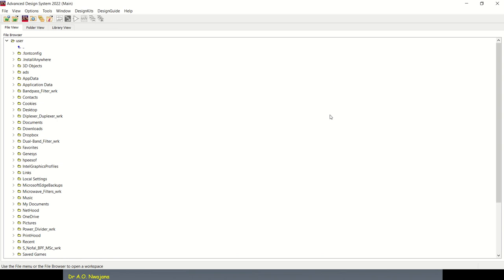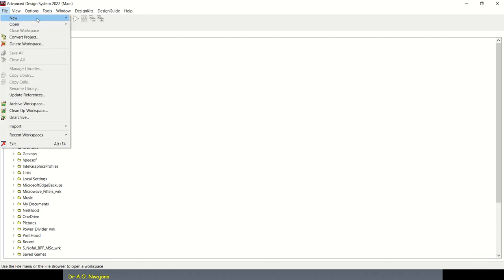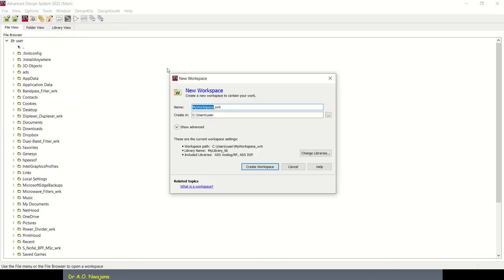Now I've launched my ADS. So the first thing I'll do is to create a workspace. I go to File, New, Workspace. For this workspace, let's just call it layout design.